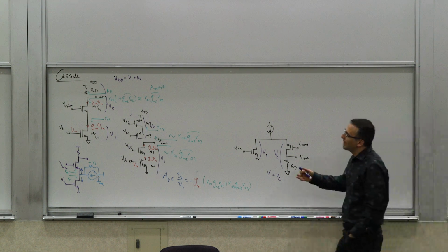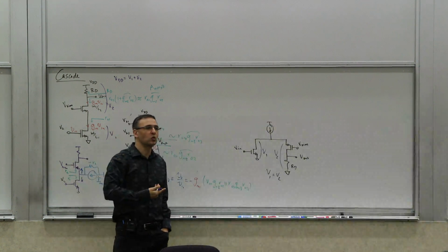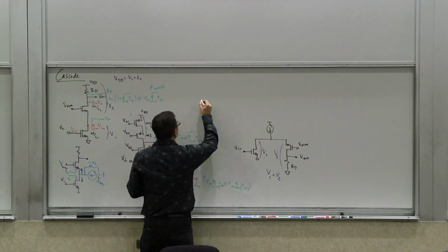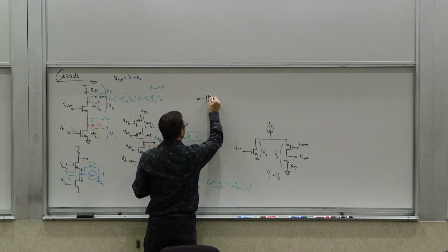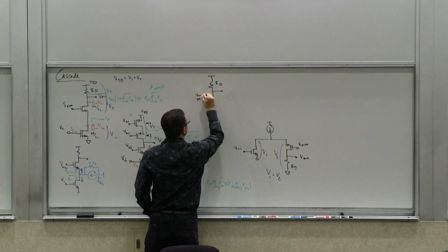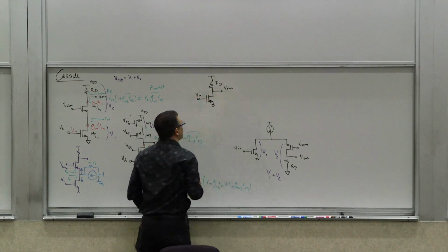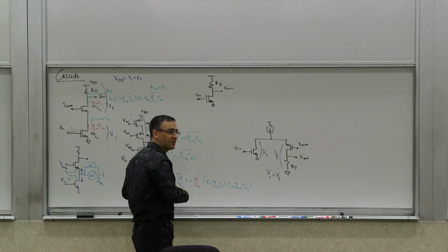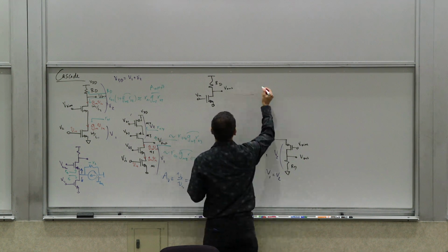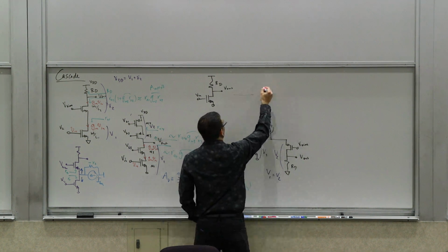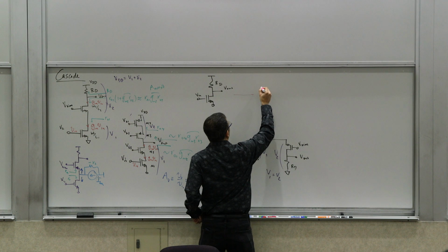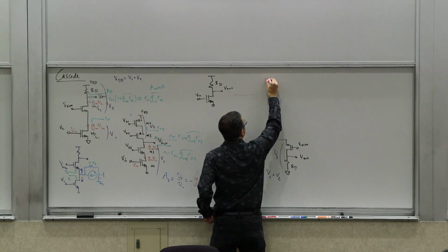Now, whenever you have NMOS and PMOS, every stage has an inverted dual, right? You can flip it upside down. So if you start, for example, with a common source, let's say, with RD, this is a basic stage, right? We've talked about this, common source like that. I can always flip it upside down and use a PFET. So the dual of this thing, if we invert it, how would it look? Well, I can use a PFET instead of an NFET, a P-type device.